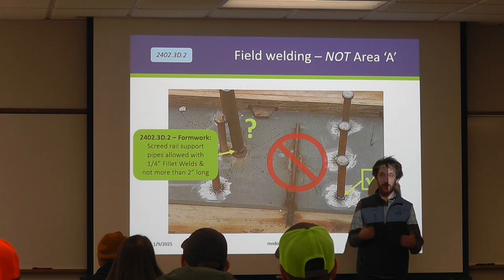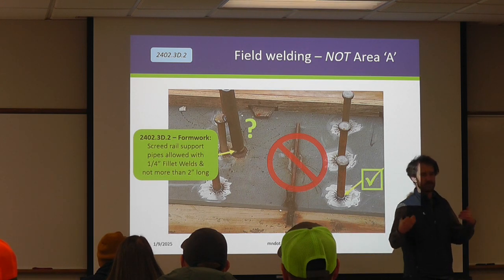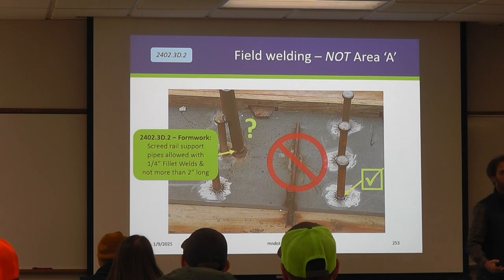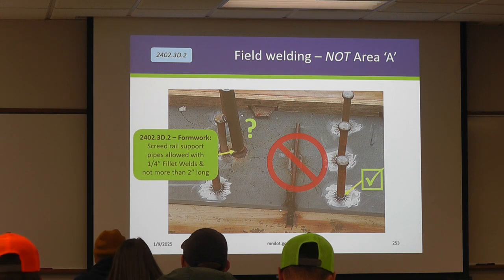Bad welds, when subject to tension, crack. Cracks turn into fractures, fractures turn into bridges sagging. Does that make sense? So generally, if they want to get the welder out and start welding on the bridge, stop them and ask a lot of questions.